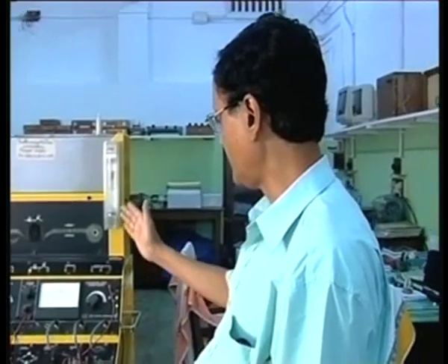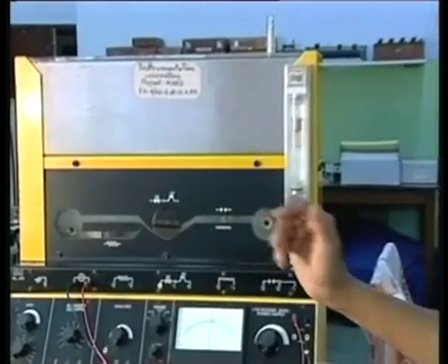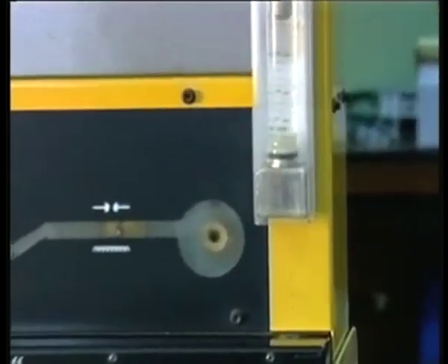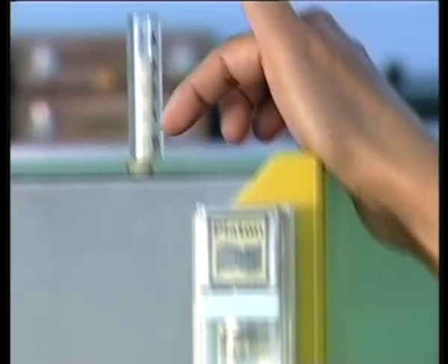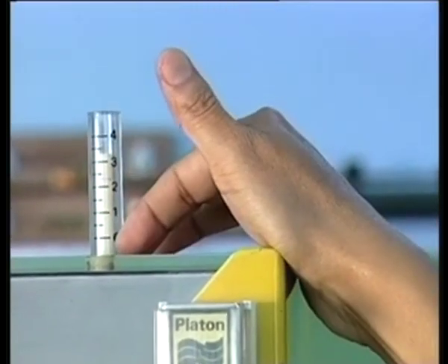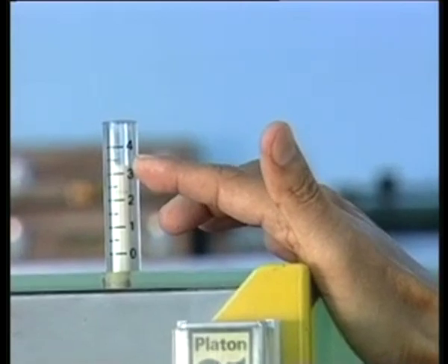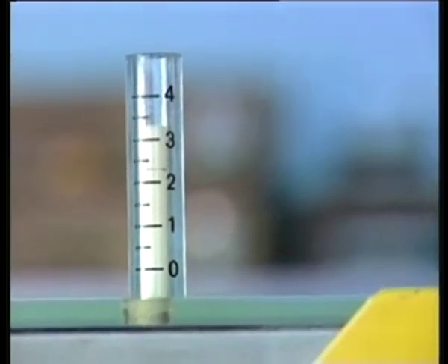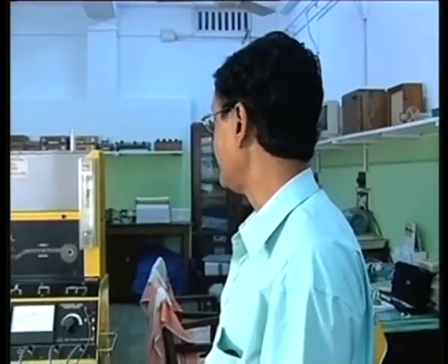In this assembly, you can find several flow meters. There are rotameters, there is an optical flow meter, there is a hot wire anemometer, and there is also a magnetic flow meter. On the top of it you will find a weir, which is called a V-notch weir. As you know, flow meters are of different types. Some of them are for the open channel and some are for the closed channel. This V-notch weir is basically an open channel meter, extensively used for irrigation purposes, to estimate how much water is needed in different fields.